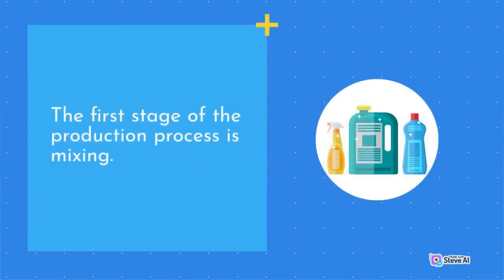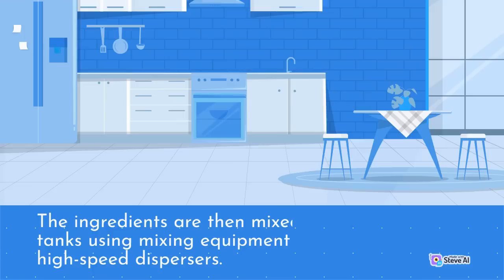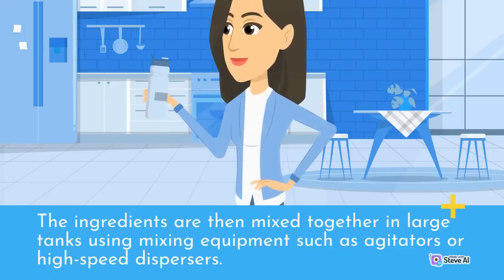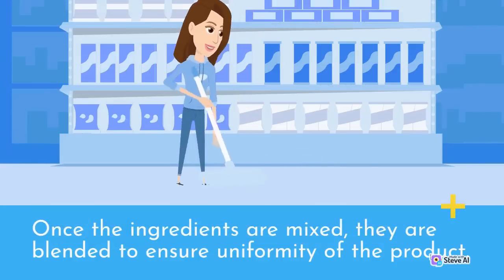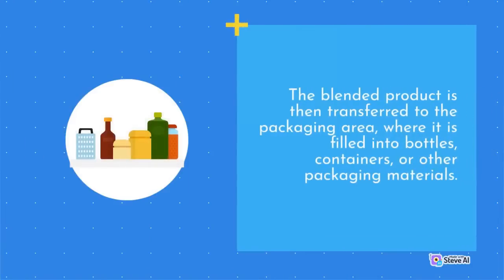The first stage of the production process is mixing. The ingredients are weighed and measured according to the formulation of the product. The ingredients are then mixed together in large tanks using mixing equipment such as agitators or high-speed dispersers. Once the ingredients are mixed, they are blended to ensure uniformity of the product. The blended product is then transferred to the packaging area, where it is filled into bottles, containers, or other packaging materials.